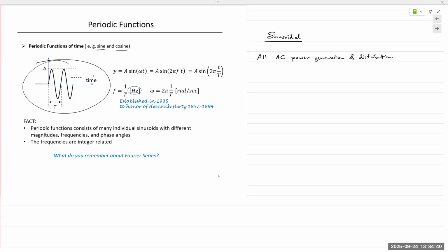Okay. An appliance obviously is not going to have any output, so it'll only say input. But a laptop adapter or a mobile phone charger will have both an input, meaning you're plugging it into the power outlet, so it has some input coming in, and then there's an output that goes into your device. So it has both input as well as output. So if you look at those, it will tell you it is 110 volts, 120 volts AC, 60 hertz, and output is 5 volts DC. You can look it up right now if you have one. It's admittedly easier to look up a laptop adapter rather than a mobile charger, but it still is required by law. So all adapters, no matter where you buy them in the world, will have it printed right on top.